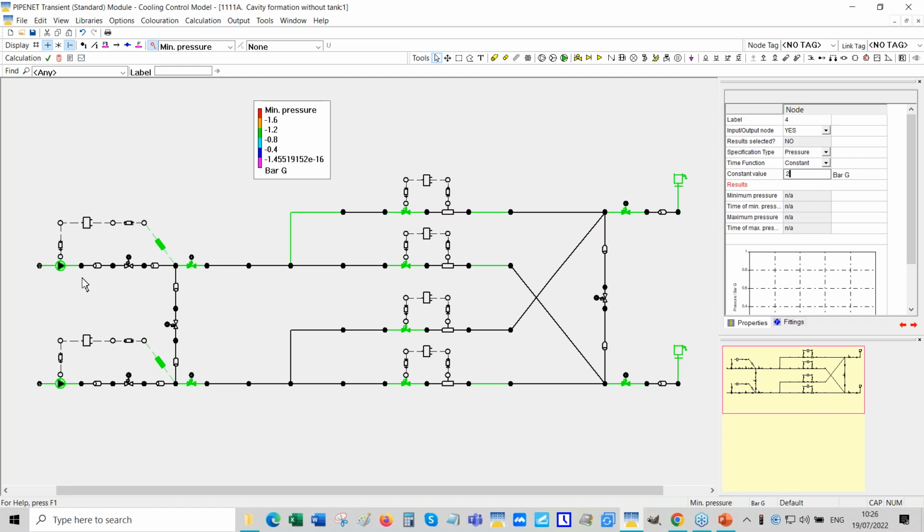Now, please remember that that is not going to increase the pressure here by 2 bar. Because when you increase the pressure here, the flow rate through the system will also increase. And when it increases, the pressure surge, or the vacuum here, you can expect it to be such that it will not increase the pressure by 2 bar. It will increase by less than 2 bar.